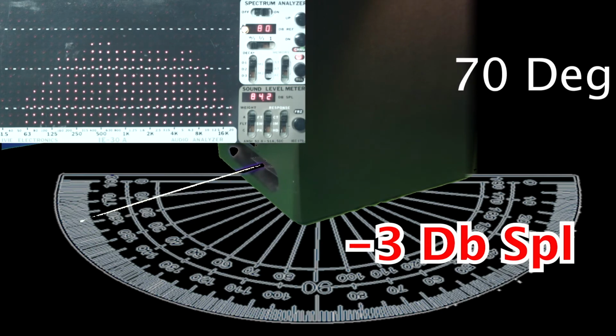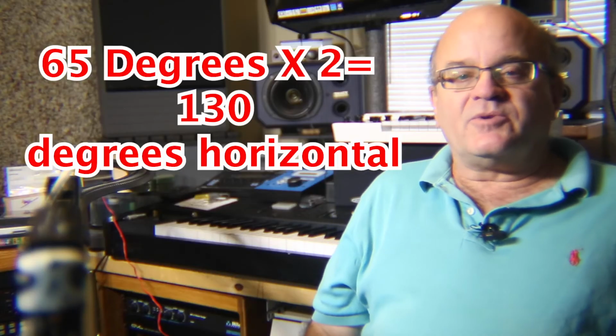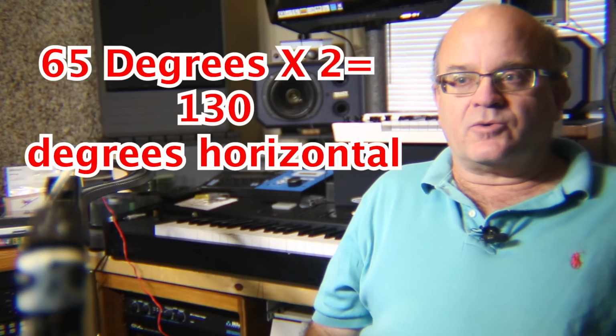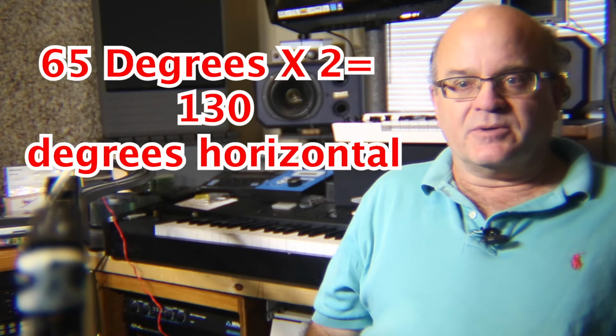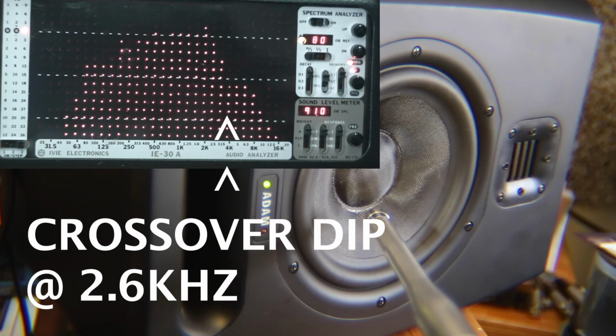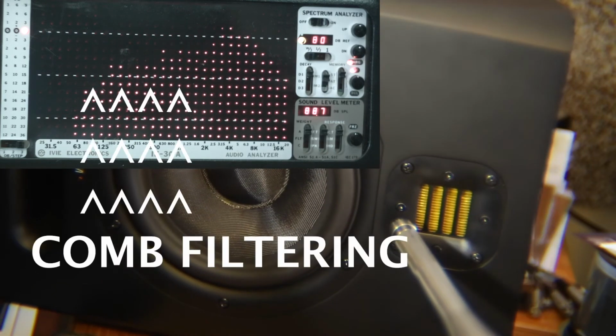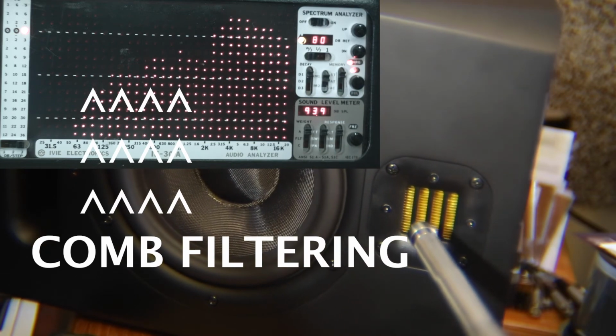Typically, when it falls off by 3 dB is what we call the fall-off point. If we multiply that angle by 2, we get the horizontal dispersion pattern of the speaker. To find the vertical dispersion pattern of the speaker, we simply turn the box on its side and repeat the process. We use pink noise for these measurements because for this example, it's the simplest method. If you put single tones in, you could measure the dispersion of the woofer with tones below 2.6 kHz. And with the tweeter, we'd measure the dispersion with tones above 2.6 kHz.